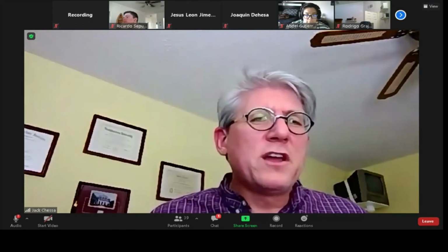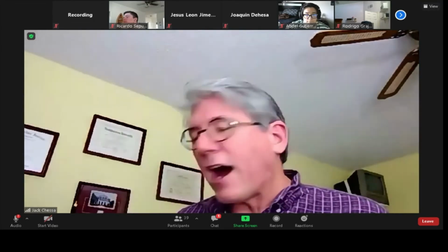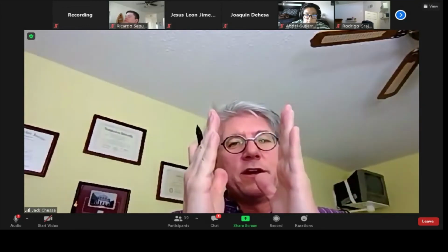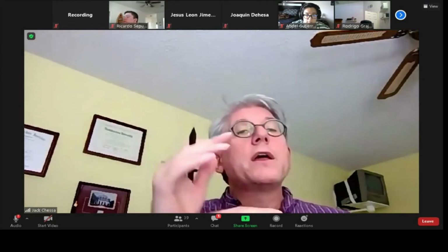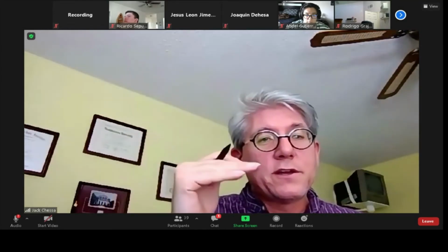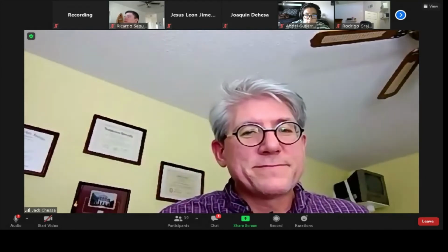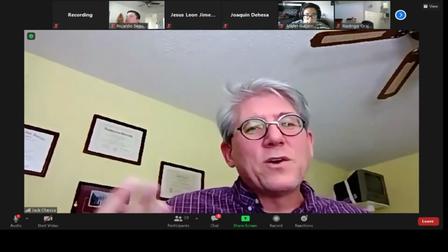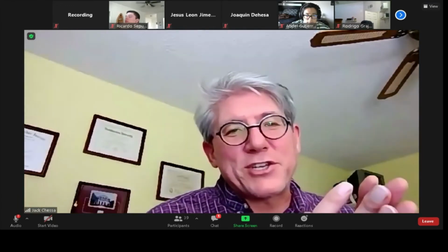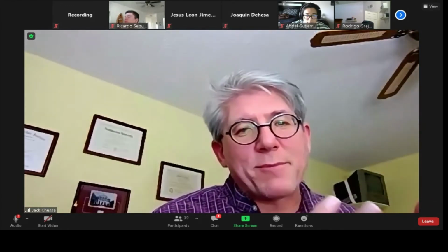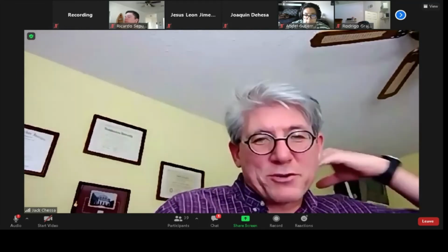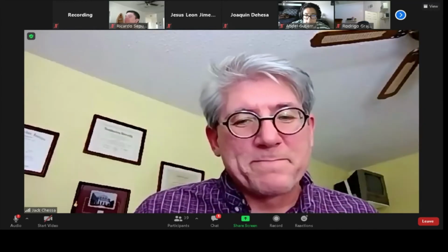For the same amount of material, you'll get a much higher I. So you'll increase the stiffness of the chair when it bends due to lateral loads, and you'll also significantly increase the buckling load. I use the chair because it's something physically we can imagine. Even if you made a chair with a 3/8 diameter post, I still think you would have a bit of an issue, but that's mostly for the side loads.